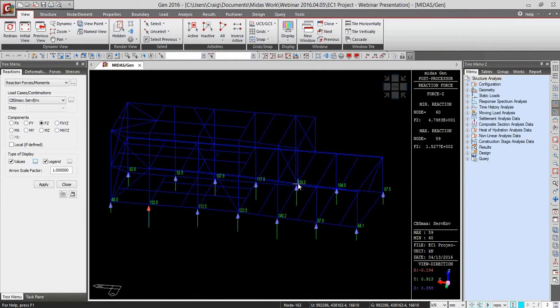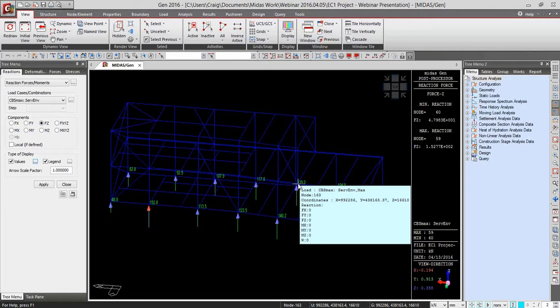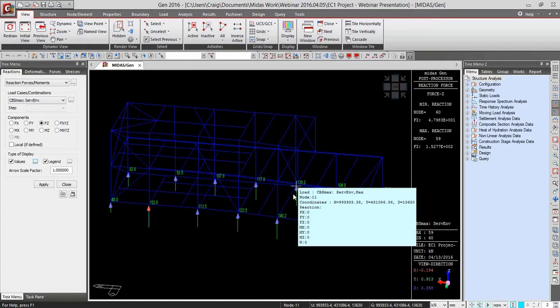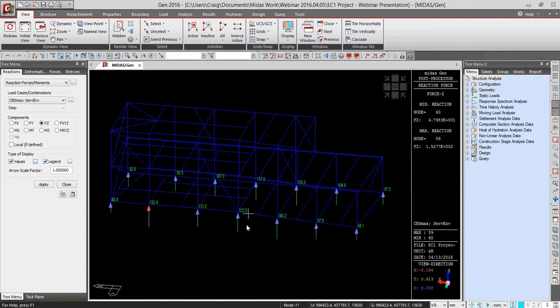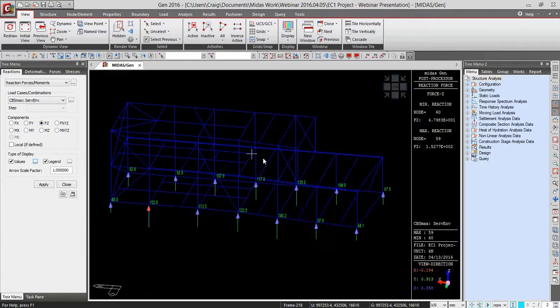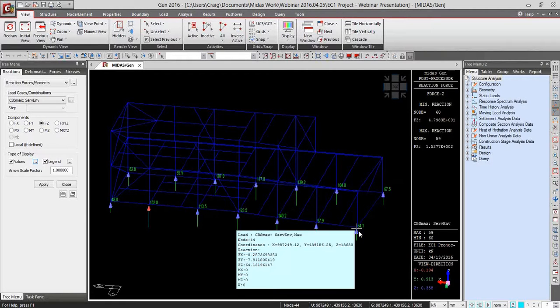So we had 3 cases of bearing pad designs when we wanted to actually support this back onto the perimeter wall. And so we had the heavier ones that are probably 140 plus. So it would be this one, and this one. They were slightly more robust. And then we had these ones where we didn't have to spread the load as much onto the masonry. And then we had the very light ones, which are on the corner as well. So they had to be slightly differently shaped.